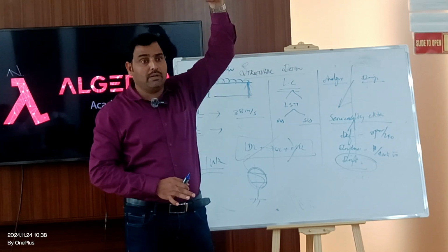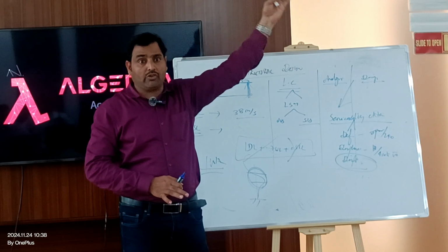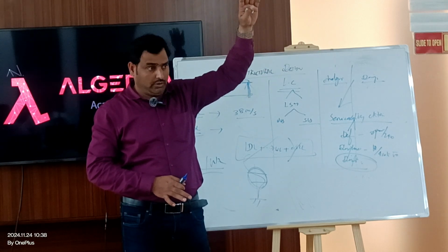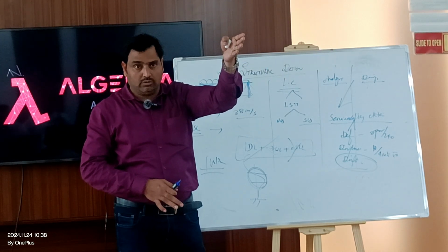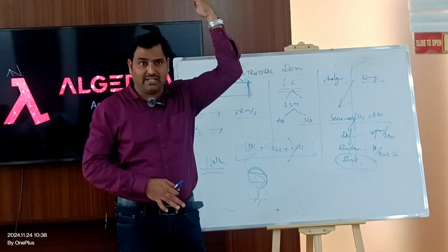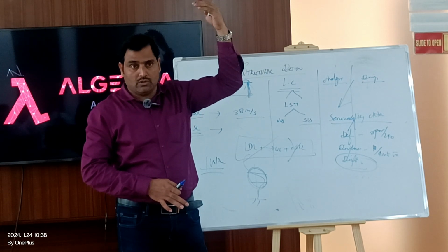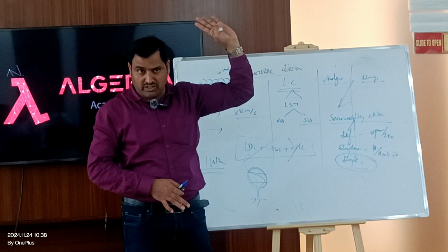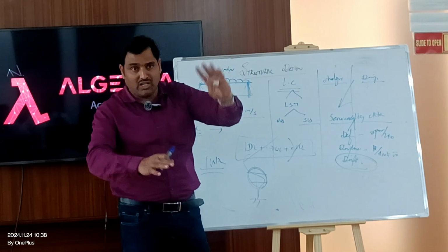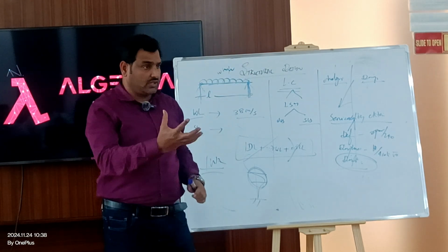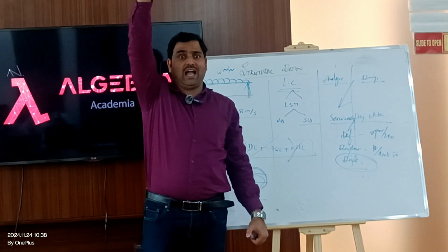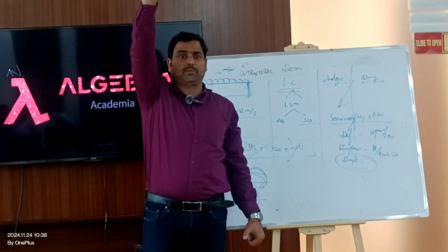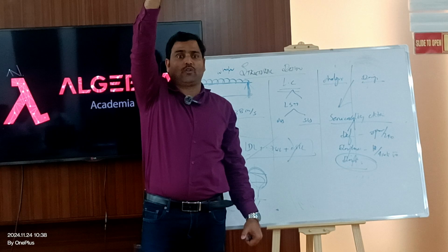I can take it as an upstand beam. I can take it as an inverted beam, which will be acting as a parapet again. You get a point. Maybe I can go for a concrete parapet. So it will be acting as complete inverted beams. So those things will directly counter the wind. So it's all required by stiffness. Here, the direct point is that where I have the maximum displacement at wind, I can directly provide the stiffness at the roof.